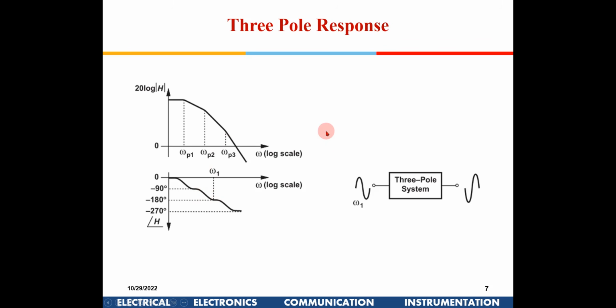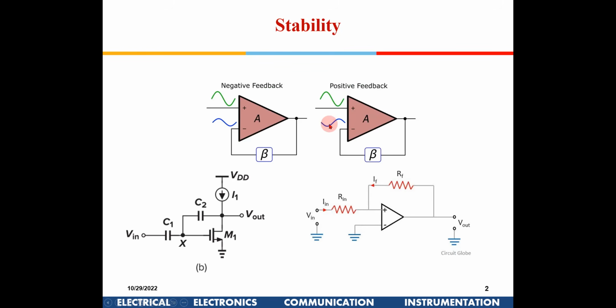So when you are giving a feedback network, if there are 3 poles, there is a possibility that by the time your signal moves through your forward gain and your feedback system, it gets inverted. Why is the signal getting inverted? Because if it reaches 180 degree phase shift, the signal gets inverted, and with the minus sign out here, plus and minus, you will reach an unstable condition.